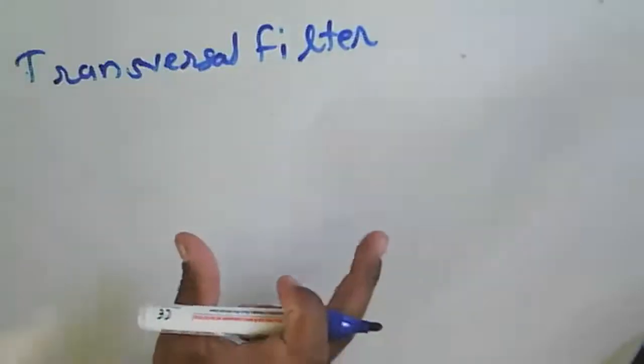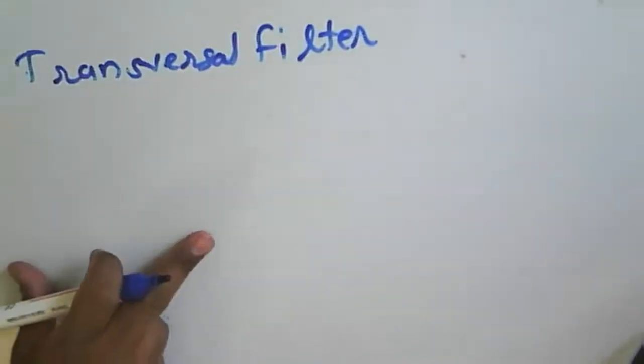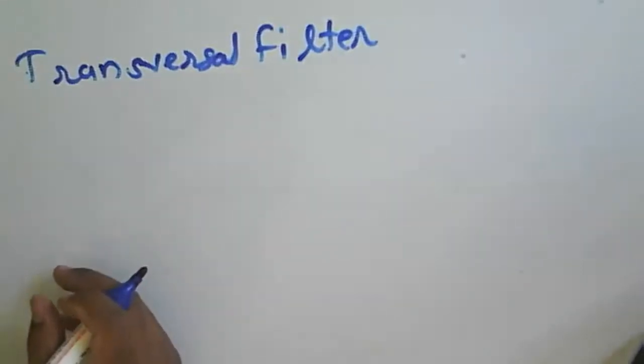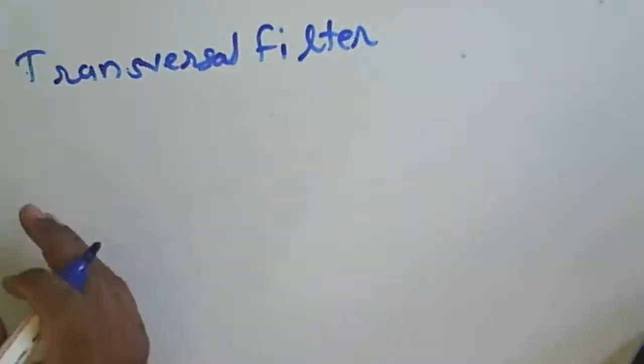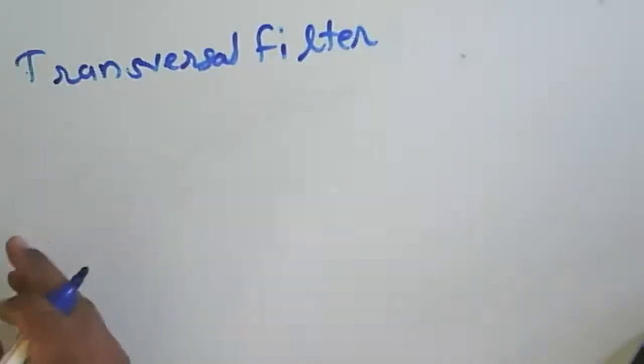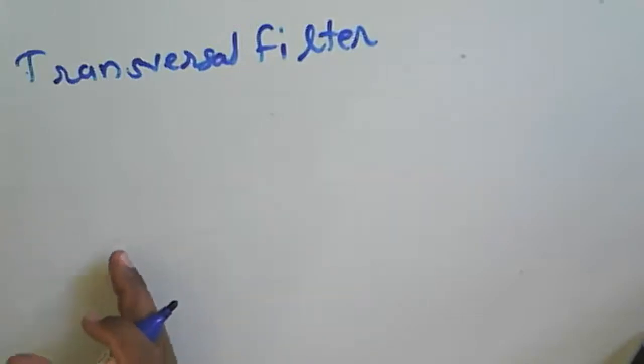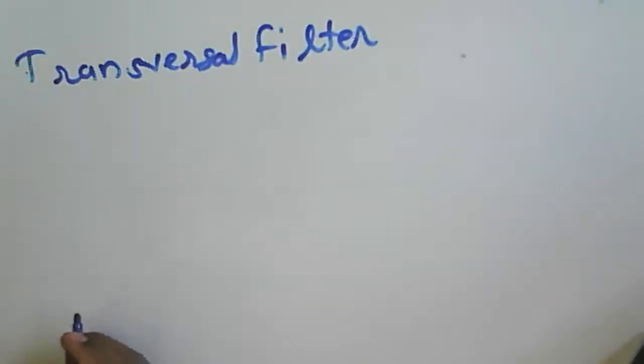The 3 pulse canceller we saw earlier is again an example of a transversal filter. If in general we have n delay lines, then the weights are applied to the given pulses, and then we combine them, so that we get a transversal filter operated in the time domain.